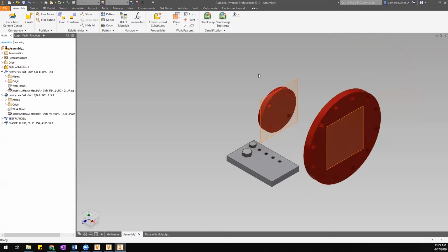Okay. Just one important thing to remember about replacing a family template is you have to start with a part placed from that family. If I try to replace it with a part that came from another family, Inventor is just going to say, sorry, you can't do that. You have to place as custom from that family. So that's why I created the copy of the family first.